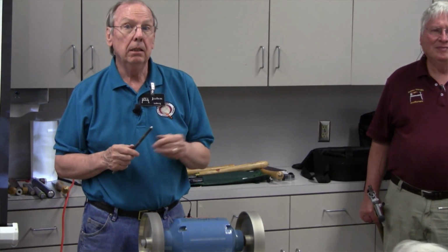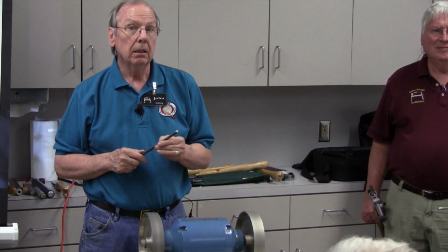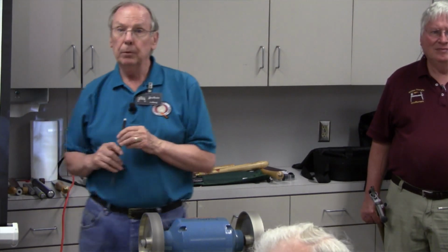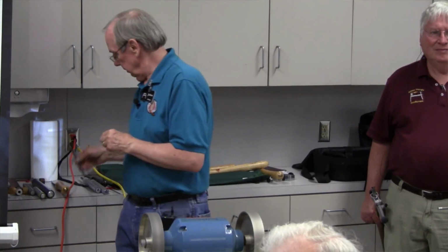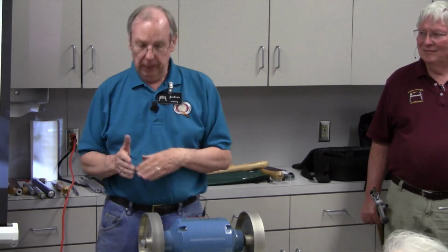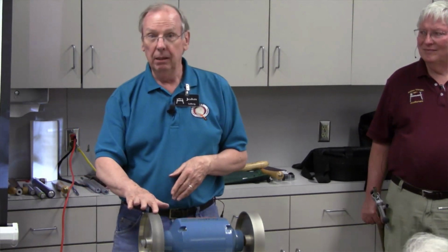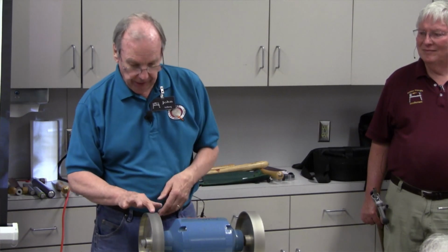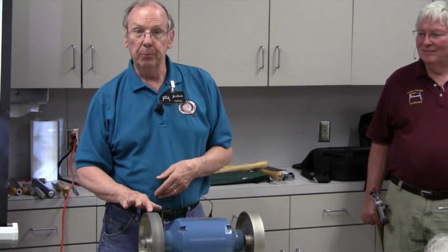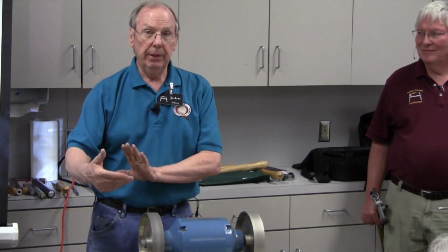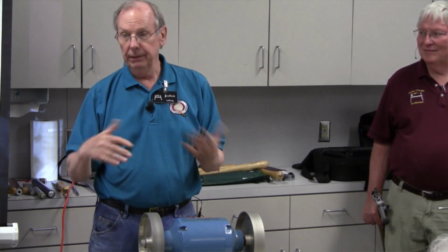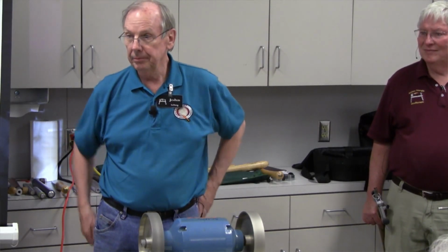When you were sharpening that gouge, you were keeping it in the middle of the grinding wheel, versus sweeping it. John's comment was that when I was sharpening the gouge, I was keeping it in the middle of the wheel. And I try to do that. If you look at this wheel, it almost looks like a wear mark right in the middle. But I like to keep it as close to the middle as I can so that it holds the angles the way I want them.